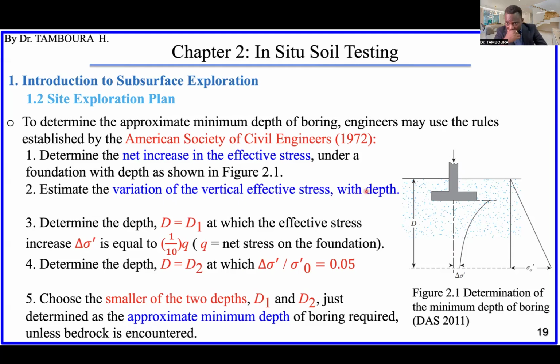I will explain the difference. Here we have a footing, and the position of the footing is here. Immediately at this position, do you remember the force, the load coming on here divided by the area of the footing will give us the stress of this footing.